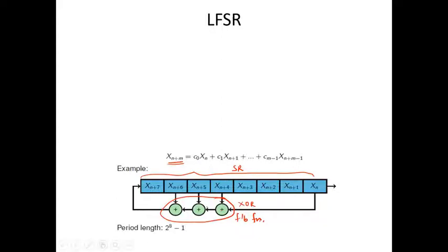So here you have an option of using multiple 2 input XOR gates, or you can also use a single XOR gate with all the inputs connected to the same gate. It can be a 4 input XOR gate where I can put x(n+6), x(n+5), x(n+4) and xn. All of these can be connected as inputs and the output can be connected to x(n+7). This can be used like this or like this, both are correct.